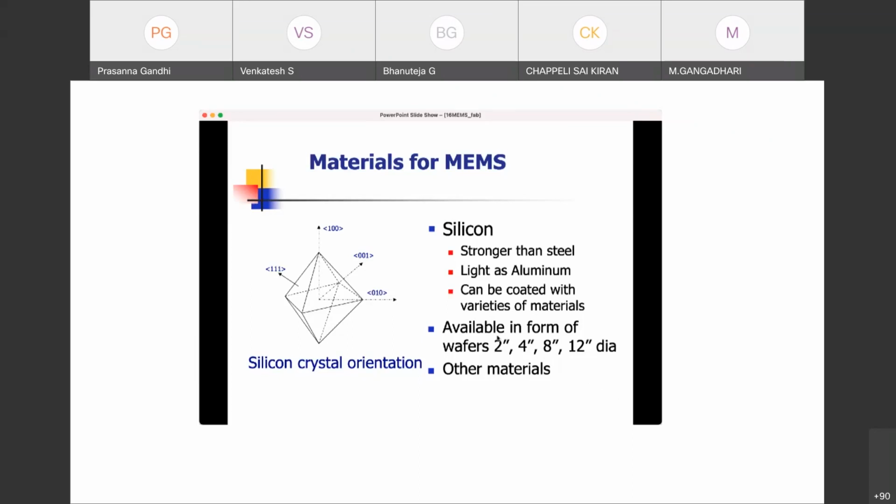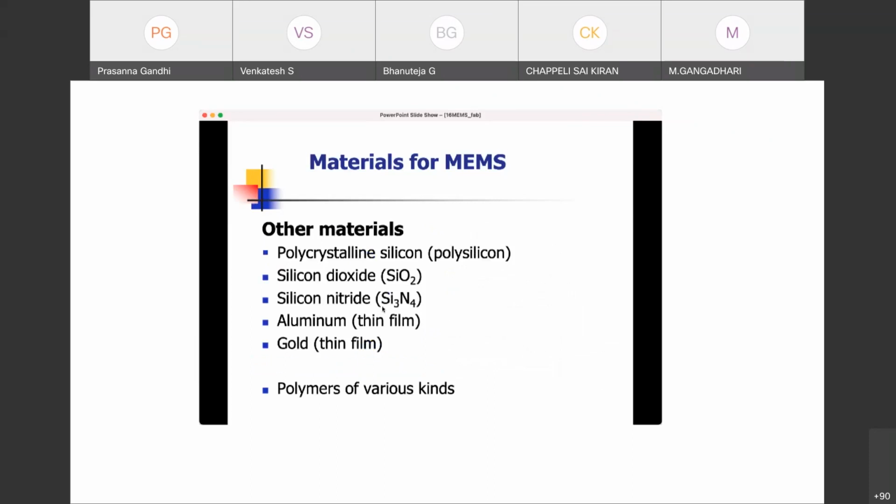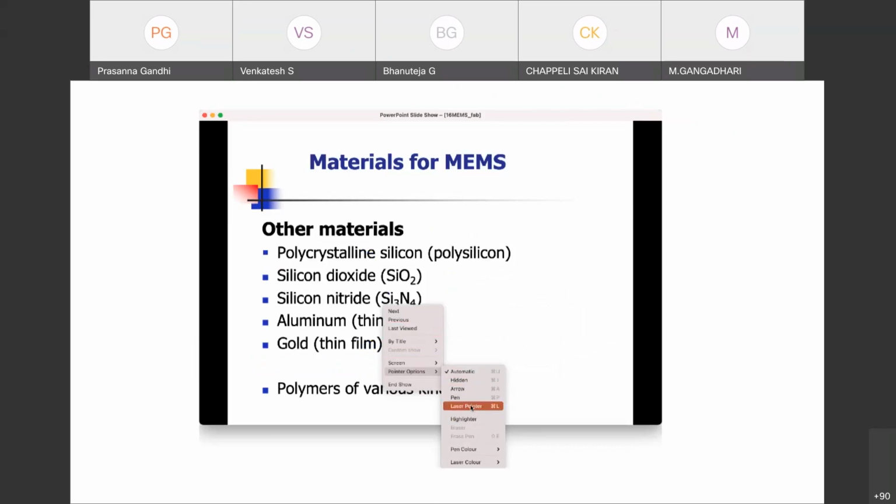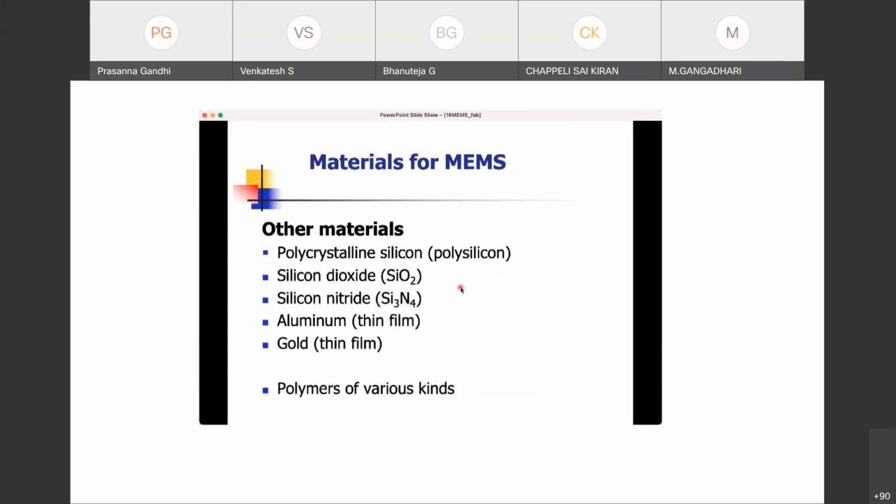And there are many other materials that are possible which can be deposited on the surface of silicon, and I think I have a list of some of the materials there. Okay, so these are only a partial list. There is a huge number of materials people have been investigating and using, including piezoelectric materials and things like that. But these are the typically traditional materials used in chip fabrication technology. And typically gold, aluminum, copper, those metal materials are used for making contacts. Okay, or you have some kind of contact lines which are made up of those materials.